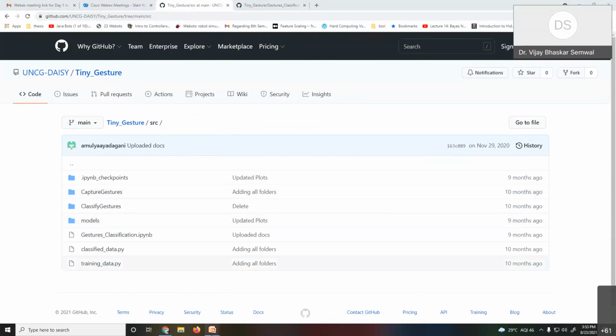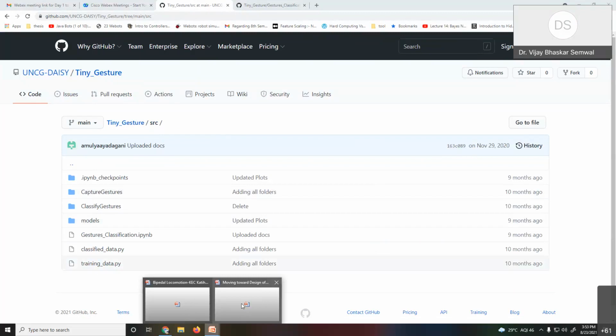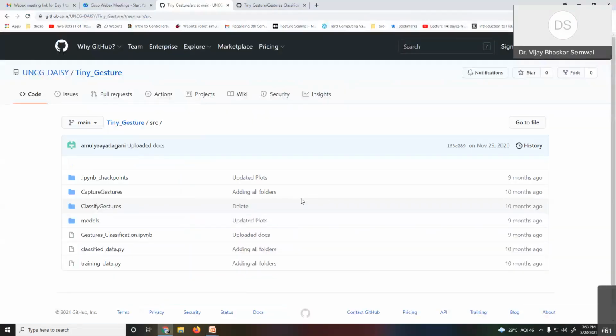Thank you. That was all about my talk. In the concluding remarks, I can say that we have explored human gait and health monitoring as an IoT application, as a cyber-physical system, and how different wearable and Kinect sensors can capture the data. Later on, we switched to the Arduino Nano BLE Sense embedded device to support edge computing. We have seen the benefits of less power consumption, fast processing, and less memory requirement. For this we have used TinyML, the TensorFlow Lite model.